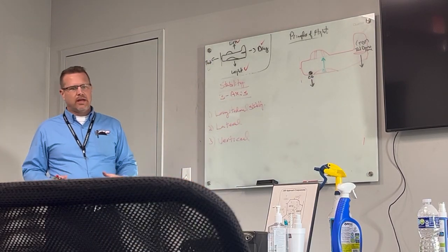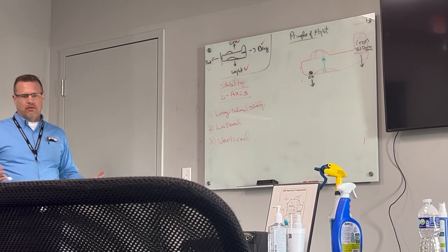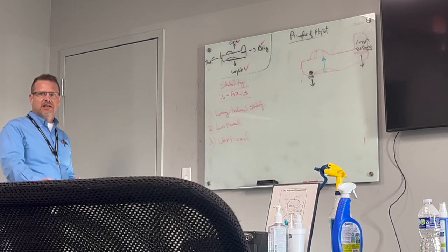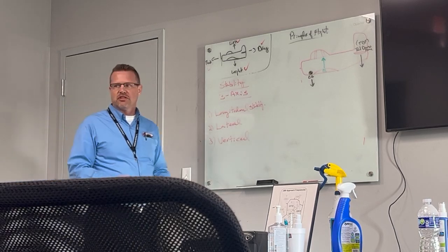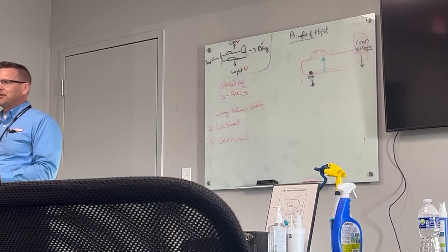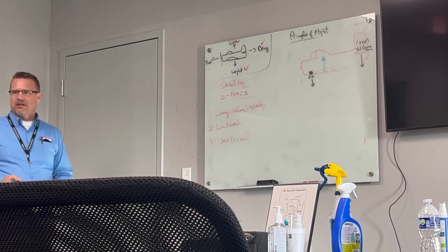So just like a wing is susceptible to all the forces of lift, Newton's third law, as well as the Bernoulli principle of velocity, an increase or decrease in velocity is going to increase or decrease lift. Well, if we increase or decrease velocity, we're going to have an increase or decrease in tail down force.